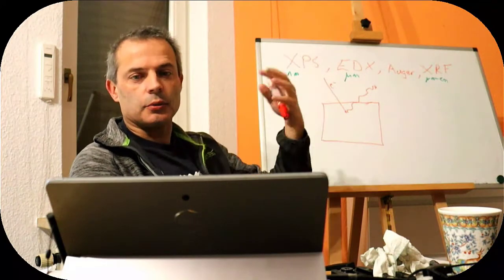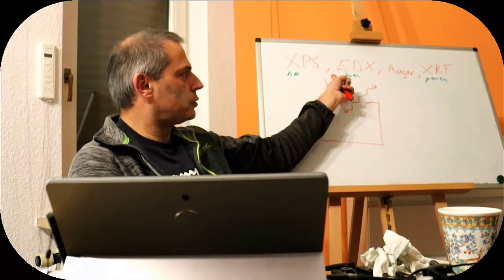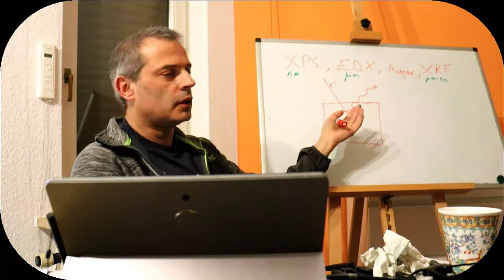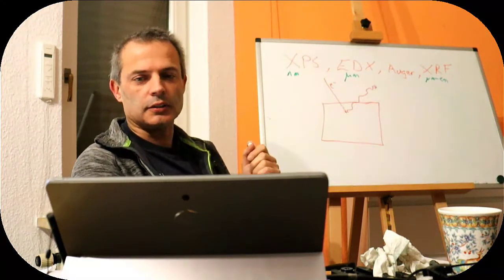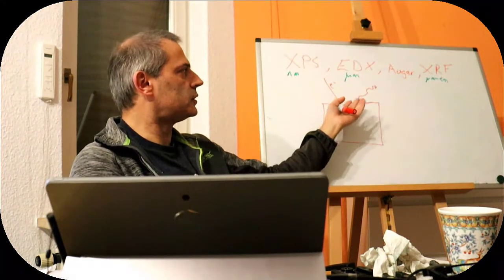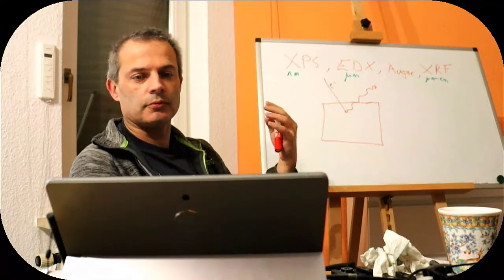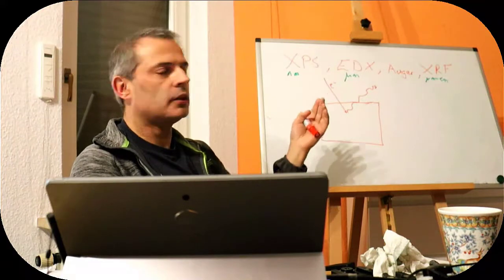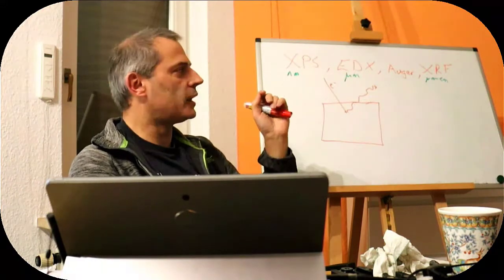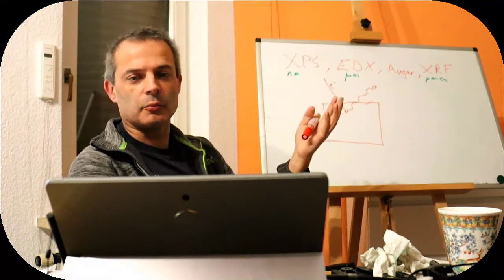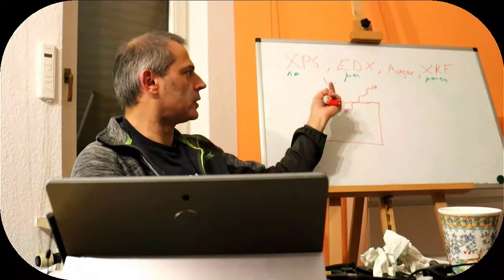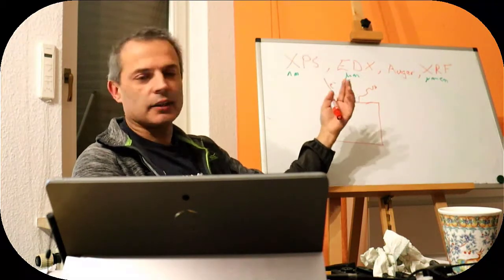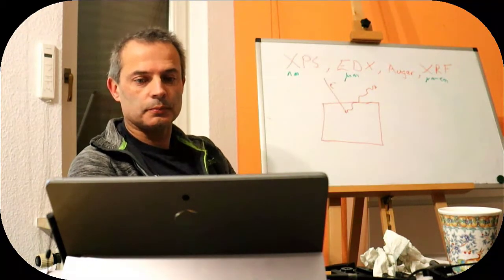So in our EDX we've got an effect where our electron beam passes into our sample and it will escape, or it will excite X-rays that can escape from a relatively high depth, and there's a toss-up between which one, the electron or the X-ray, can penetrate further. Typically the electron is the thing that's being stopped.